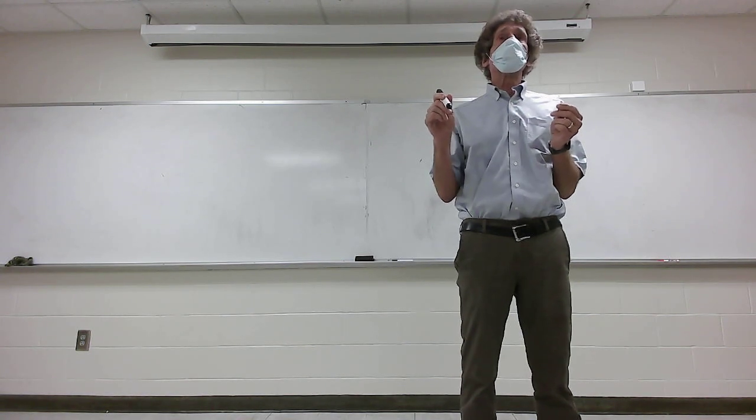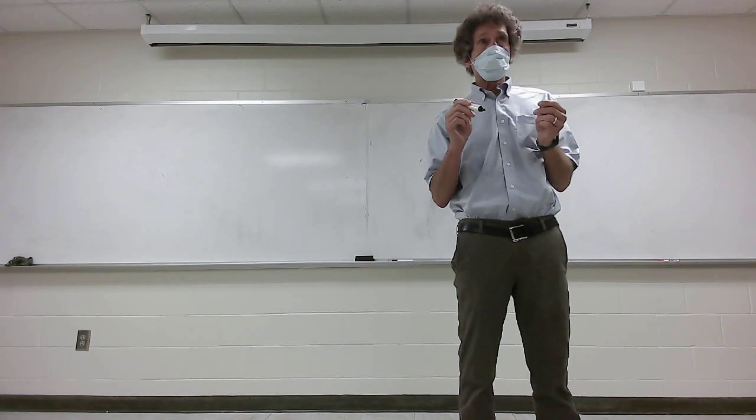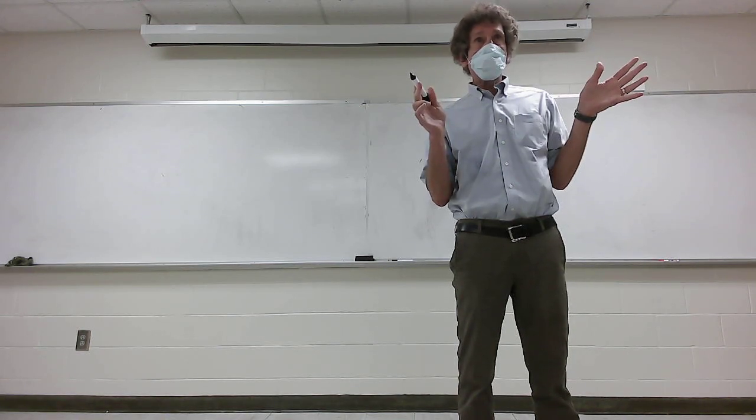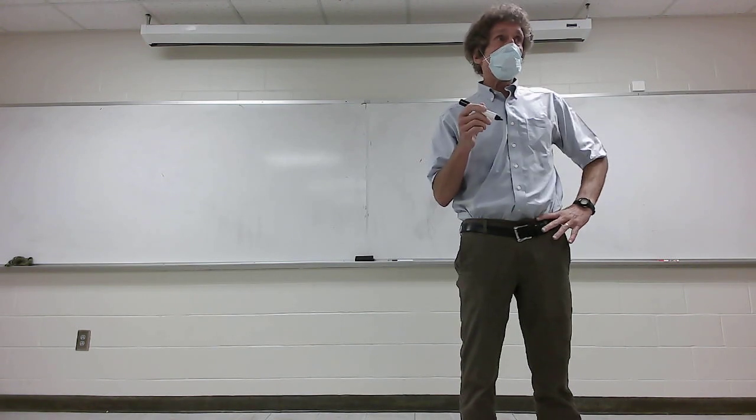No, it said RMS, didn't it, class? Yeah. All right, RMS means you have to multiply by the square root of 2 to get the peak value. And the peak value is what's used in Dr. Whitmore's formulas in the book. That's the reason I did that.